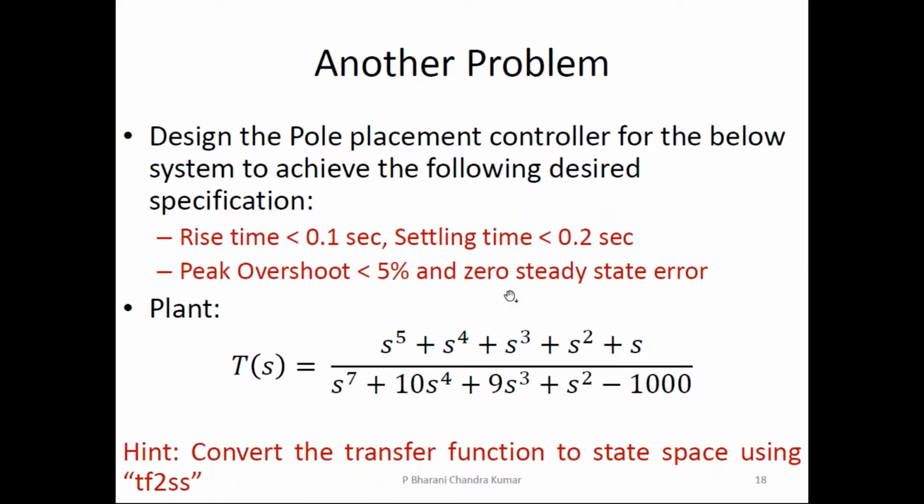You assume that the higher order terms like the Hessian and other things are zero. The partial derivative of the plant with respect to the states will give you the A matrix. The partial derivative of the plant with respect to the control input will give you the B matrix. If you substitute the corresponding operating points, you'll get the A and B matrices accordingly.